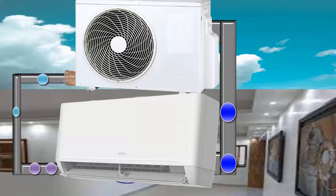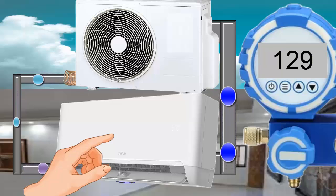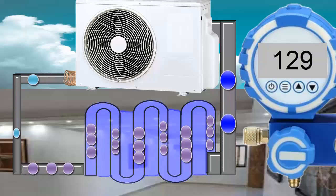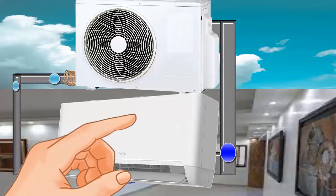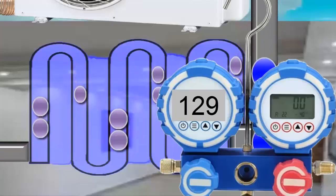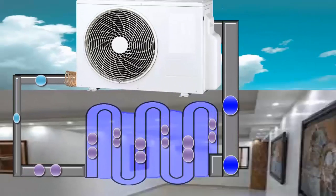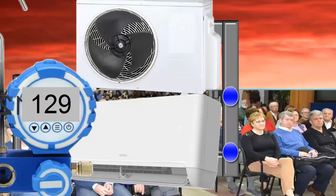The pressure of the R32 gas in the evaporator unit, indoor unit, during operation is approximately 129 pounds per square inch, psi. At this pressure, the temperature of the R32 gas inside the evaporator is around 5 degrees Celsius. Refrigeration technicians refer to this pressure as low pressure, and it is measured with the blue pressure gauge. Low pressure is not constant and varies, although very slightly, depending on the equipment's operating conditions.